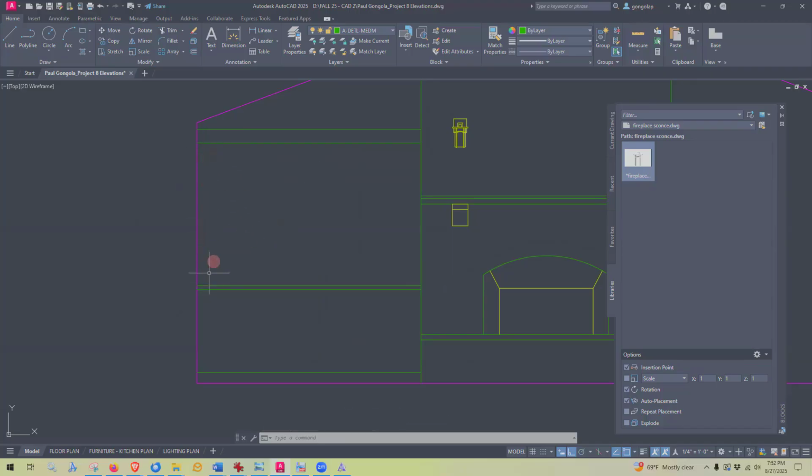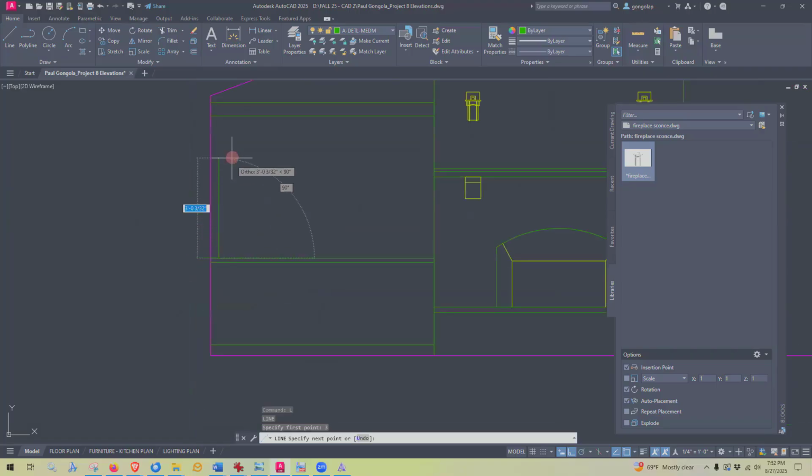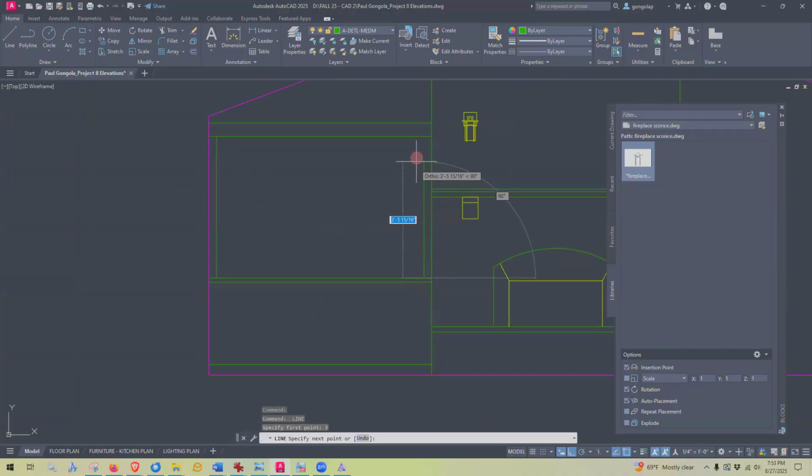So now let's look. We've got 3 verticals, or supports, that are going to hold up the shelves. And they are 3 inches wide, the trim. So I'm going to use my line tool, and I'll just start here. I'm going to O-track over to the right 3 inches and go up. And if you want, you could mirror this to get this one, but I'll just O-track over 3 inches and go up.